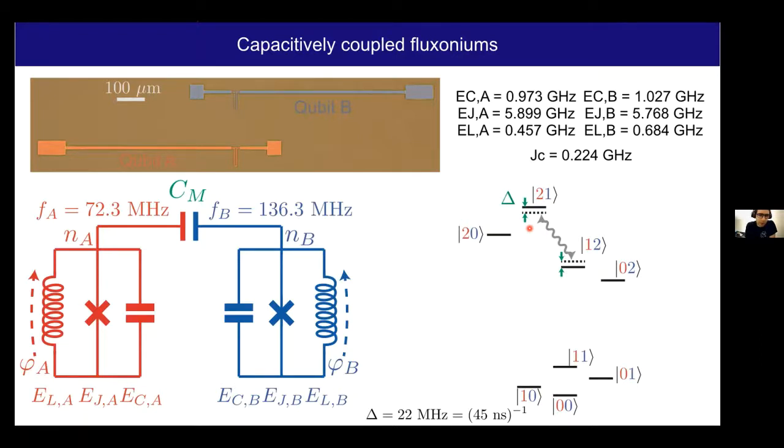You can just adapt the size of the antenna of a transmon so as to get an EC of about 1 GHz, not 0.3 GHz, which is typical of a transmon, and then you just have to replace the small junction by a junction shunted by a loop with this array of junctions, and that's pretty much it. Now on the control side, the qubit frequencies are lower, which means that we typically don't use an RF generator. We either use directly the output of an AWG or FPGA, but that's pretty much the same cables and same everything else. Okay, thanks.